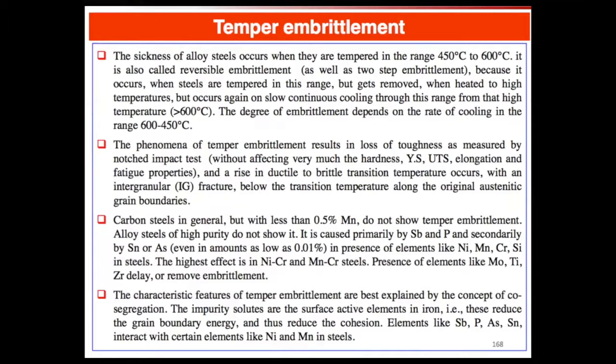And so it's reversible in the sense that if you heat above this range of 450 to 600 C and then cool back down, and hold in this regime, you'll get the embrittlement back. So basically, highlight on your, wow, this slide is so confusing. I went through it and I had a specific thing I wanted everyone to highlight.